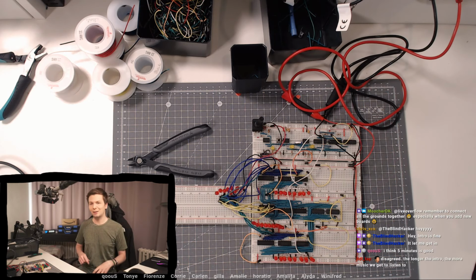So if we execute the clock, it will move now the value with the -1 into this register, which means the ALU will then calculate -1 from that and put that on the bus again. And with the next clock, we move that value in there. And through that, we basically circle around and always decrement this value. So if we execute the clock by hand, we can see slowly this register counting downwards in binary.